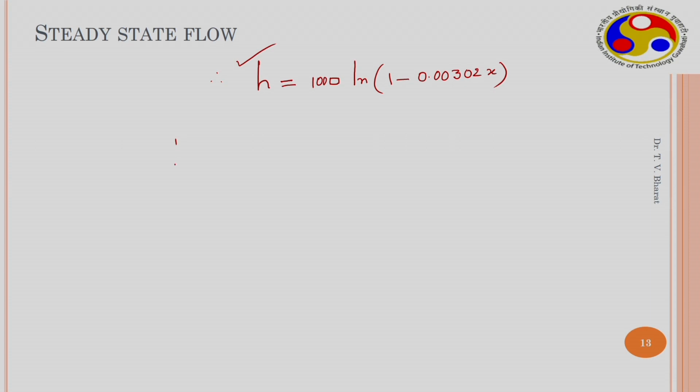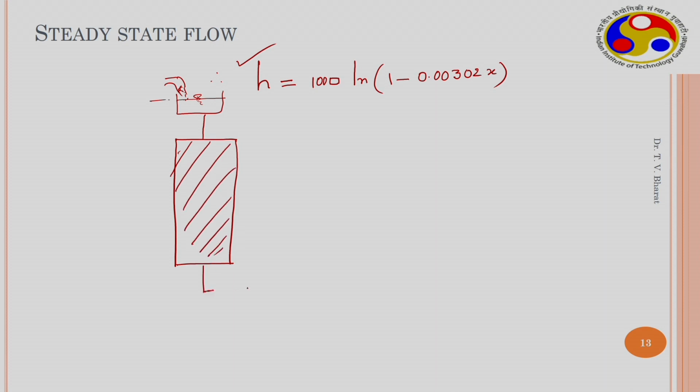So as I said, if you take a soil mass and connect to a reservoir, a constant water head reservoir, here water flux can be maintained, constant water head is maintained. So now this is a soil sample which is connected to an outlet pipe where water comes out. So you have a particular head that is maintained, constant head that is maintained across the soil sample. Now in this particular case, when you connect two manometers,